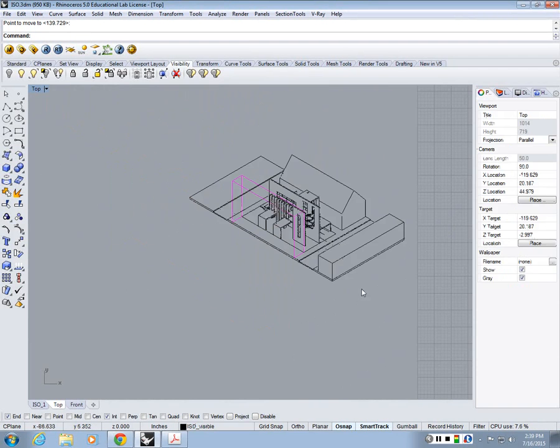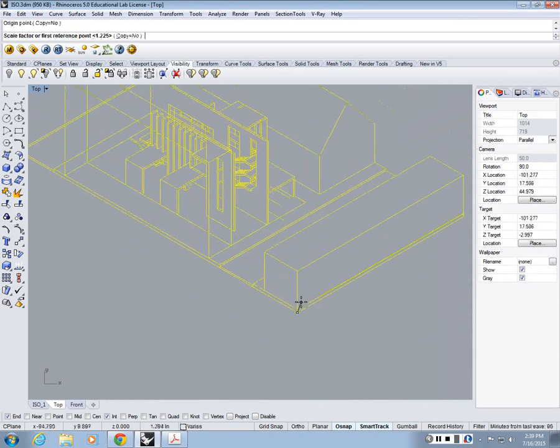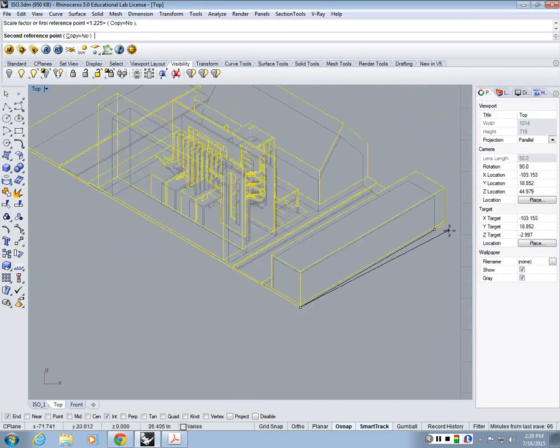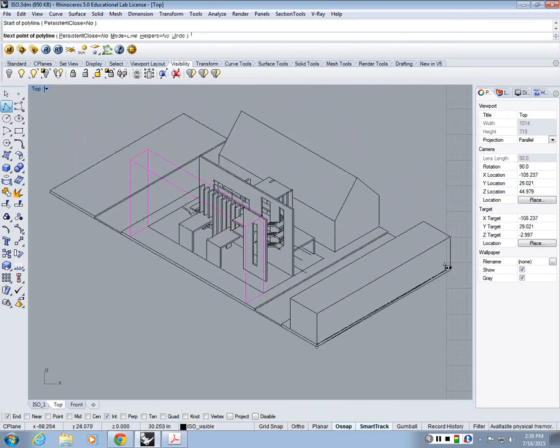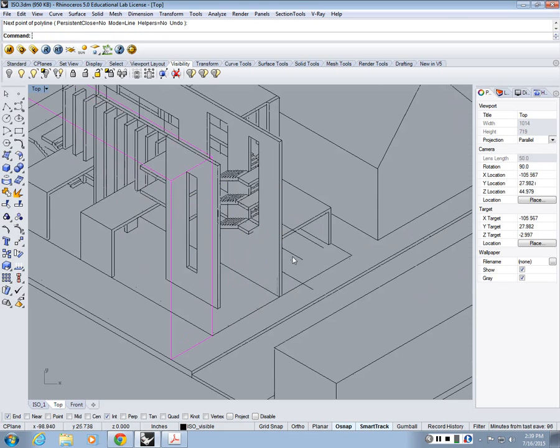Right? Then what I did was I scaled everything. I know the site width is 30 inches, so I scaled this to be 30 inches. When I do that, this is 30 inches, this is 60 inches. My wall is 13 by 21. So I have a drawing that is up to scale in all 3 views, 3 angles.